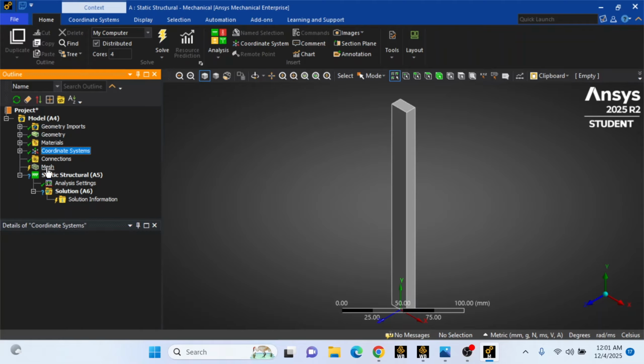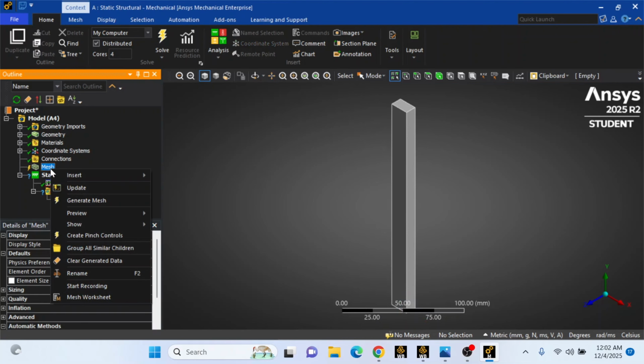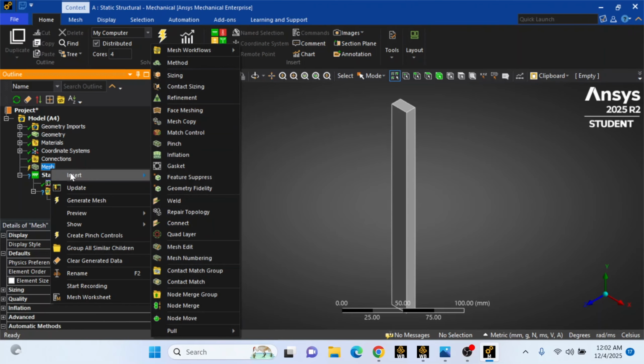You can hear a complex name for it like discretization, but for solid systems, we use something called finite element analysis. For liquid, we can use finite volume, right? But that one is in later sessions where I'll be dealing with fluids. So for now, we have our mesh here. And the quality of your mesh matters when you're simulating. It is one of the most important things you can ever do when you're doing a simulation. So I want my mesh to be very fine. There are a lot of parameters I can insert to change my mesh.